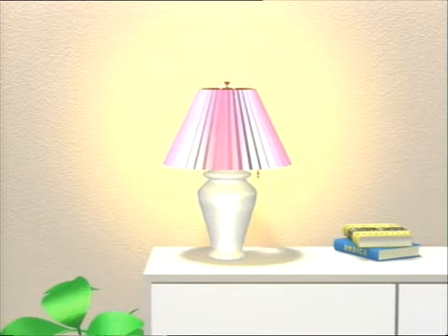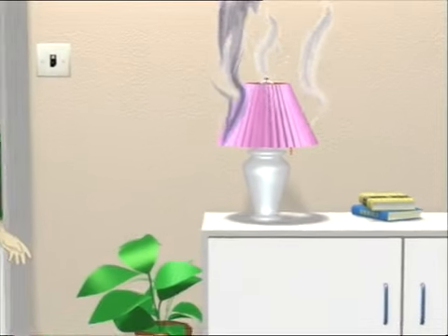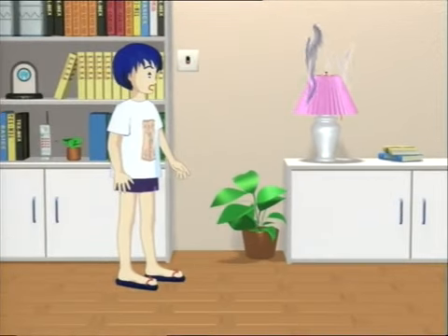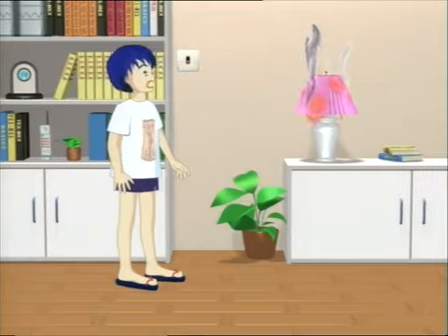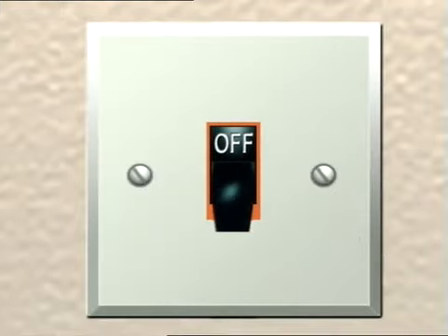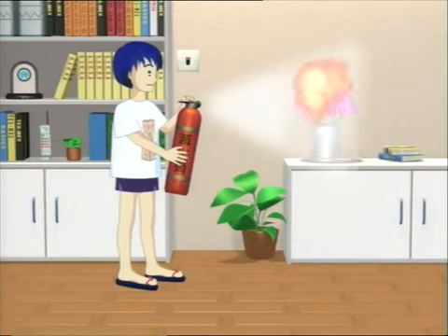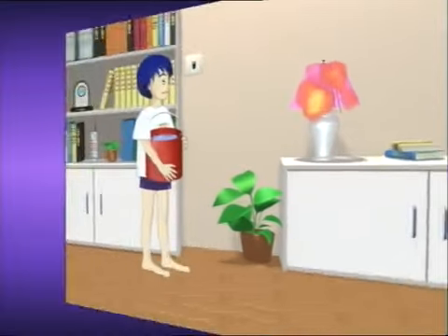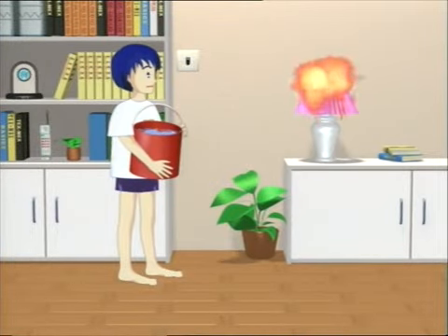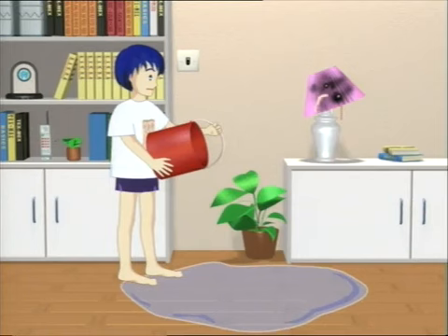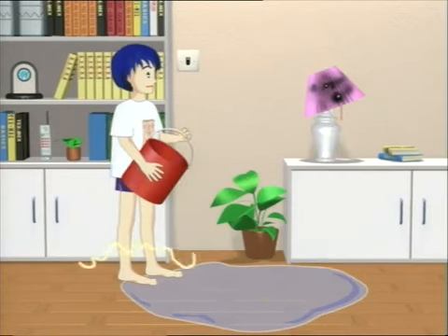In case of accidents, such as the fuming or burning of wires or sockets, the relevant branch switch or the main switch has to be turned off immediately. A carbon dioxide fire extinguisher should then be used to put out the fire. Water is not recommended in this case because water is a conductor which may lead to an electric shock.